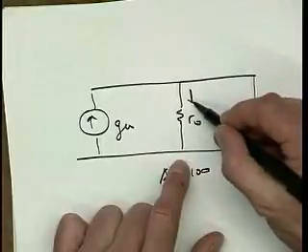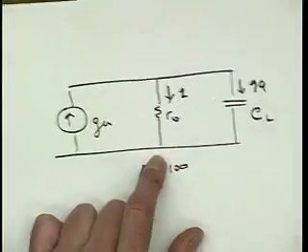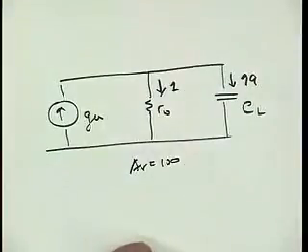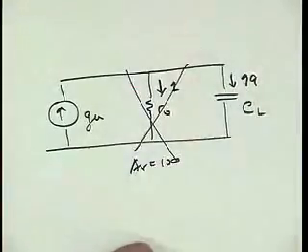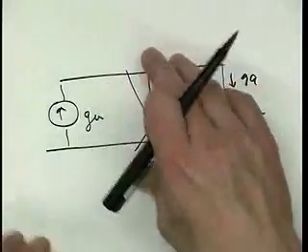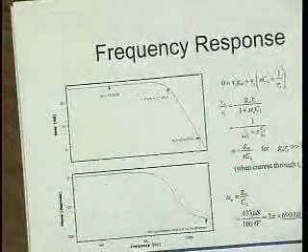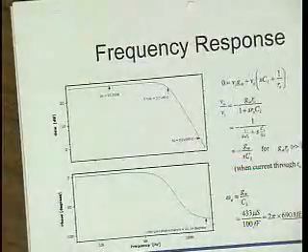So in other words, now one part of the current goes in here, and 99 parts of the current go into the capacitor. Well, it's a big waste of time then at this high frequency to include ro in the calculations. Right? So that's why you will very often see me just write down gm over CL, and that's the unity gain bandwidth of the amplifier.